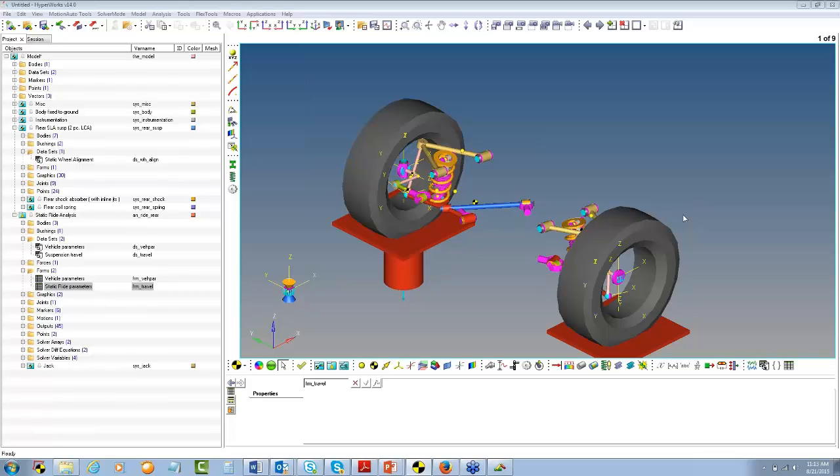For an all-terrain vehicle, I guess that should be around 5 inches, right? More than 5 inches, I see no reason why the wheel should travel more than 5 up and down. So that is 5" up and 5" down, which makes it 10 inches of travel in total. I think your axles or something might have maxed out before that.